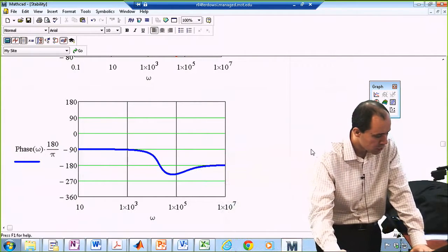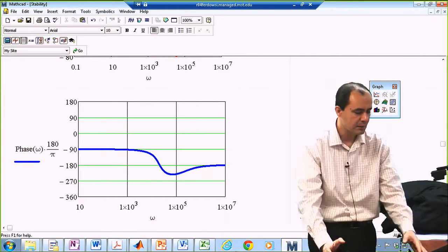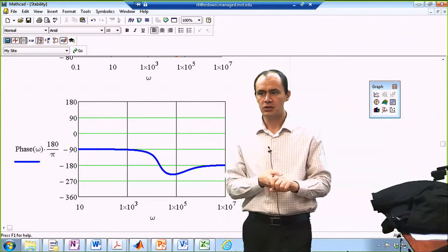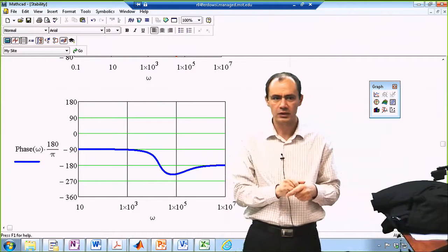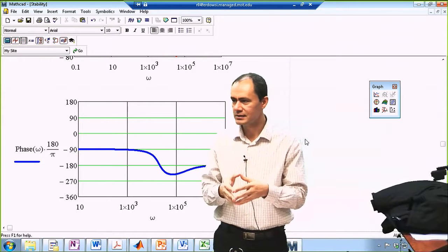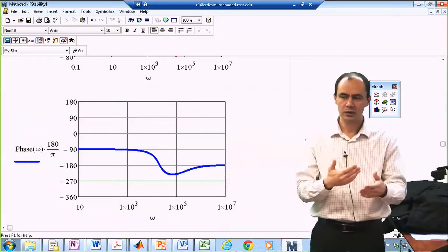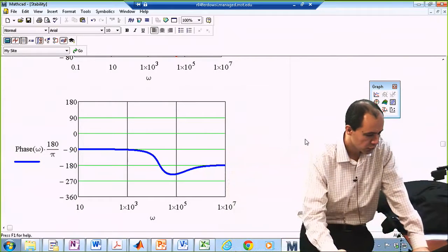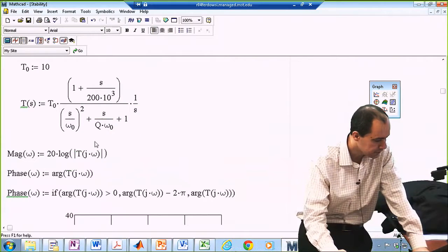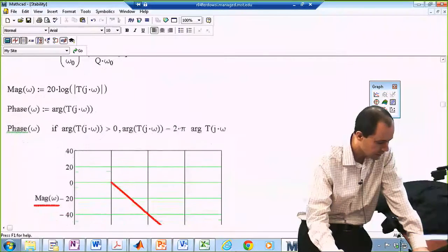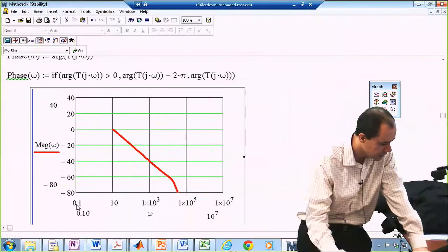All right. So now let's say you are happy with the stability of the system. You're happy that you have added an integration block in your loop to eliminate the steady state error, but the system is too slow. And in order to make the system faster, you are going to increase the gain to increase the bandwidth, basically. Okay, so let me just change this scale to 10 again.